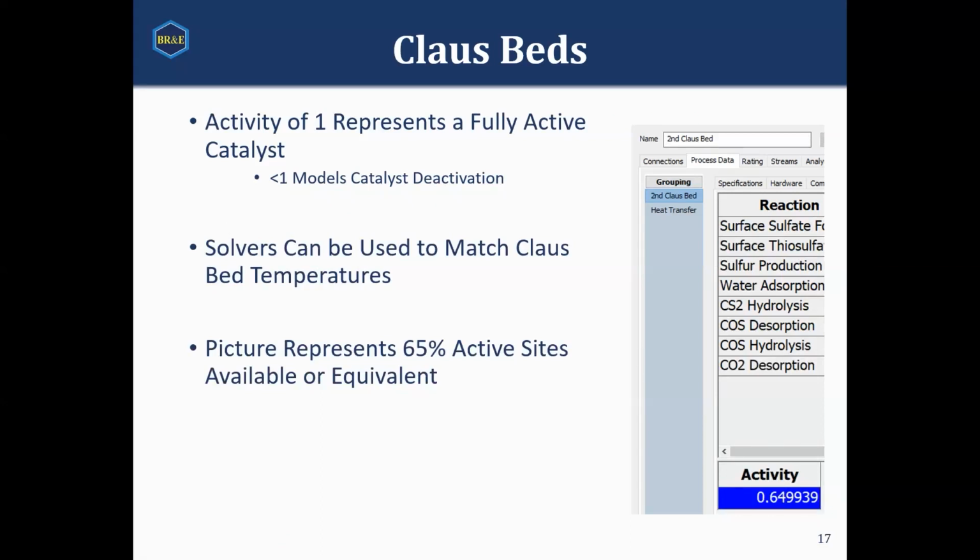That's less of an exothermic reaction occurring. So that means that the temperature difference between the inlet and outlet will not be as great as with a fresh catalyst. So the outlet temperature may start to look like it decreases over time if you're not compensating for that by increasing your reheater as time goes on.